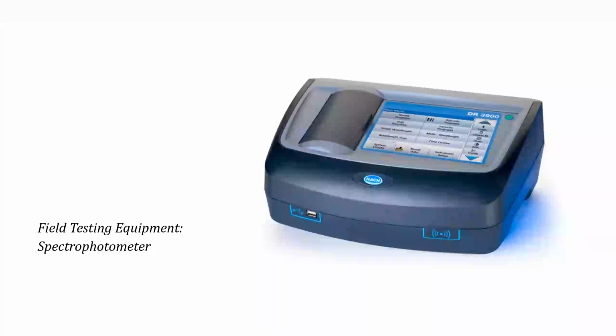And then the next best is a benchtop spectrophotometer. These are in the $5,000 or $6,000 range for the better ones. They give you very quick results, 10-minute results for the soluble phosphorus. Again, I'm interested for process control in the soluble phosphorus, so I don't bother cooking the samples to break down to get total phosphorus. I want the soluble phosphorus that goes through the plant. These instruments are so accurate that some of the tests are EPA approved.